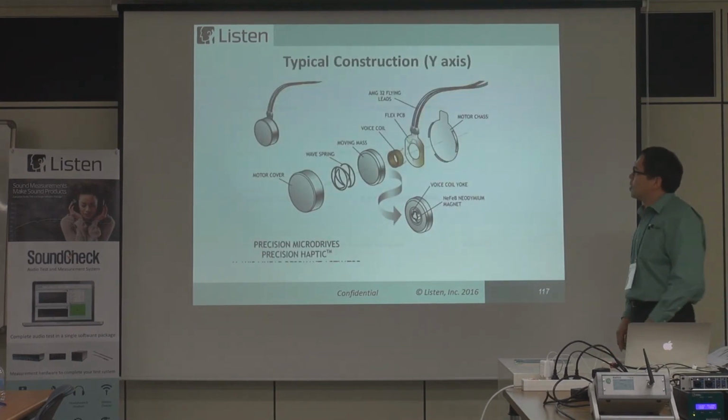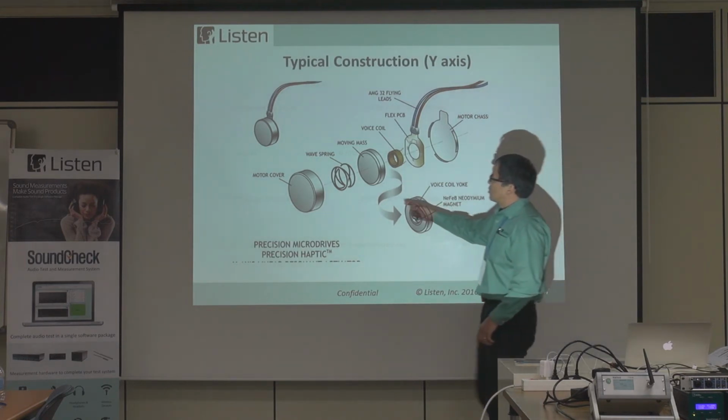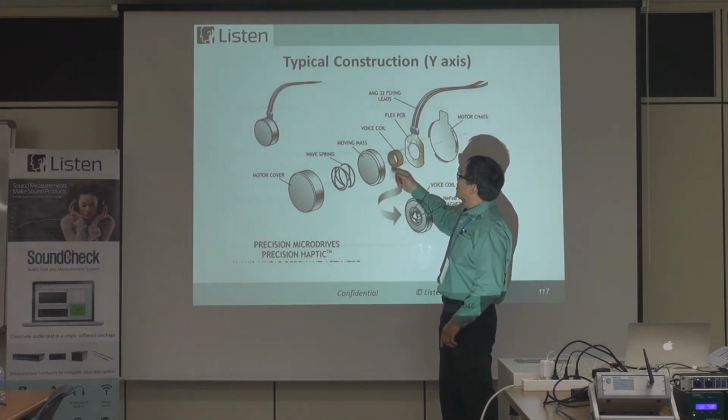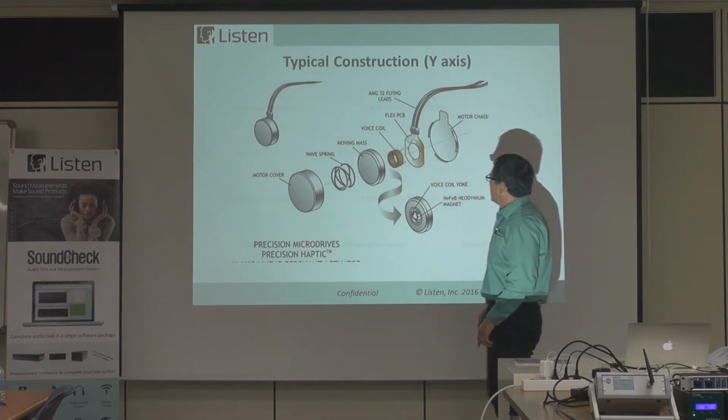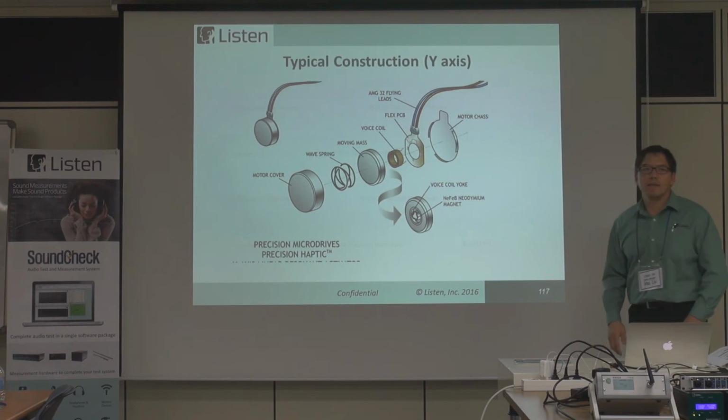And here's the typical construction of a y-axis one, so it's perpendicular to the surface you're touching. It has a spring, a moving mass, and a voice coil. In fact, it looks just like a speaker, the way it's designed.